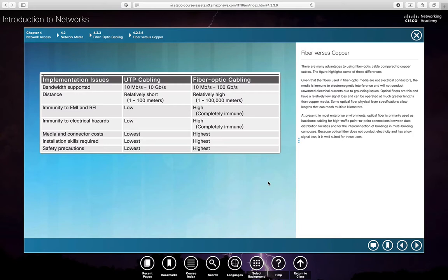Well, the answer is fiber optic, because at least at frequencies that we live with here on Earth, not on the edge of a black hole, electromagnetic interference cannot alter light. So you would want to use a fiber optic cable so there's no chance of electromagnetic interference.